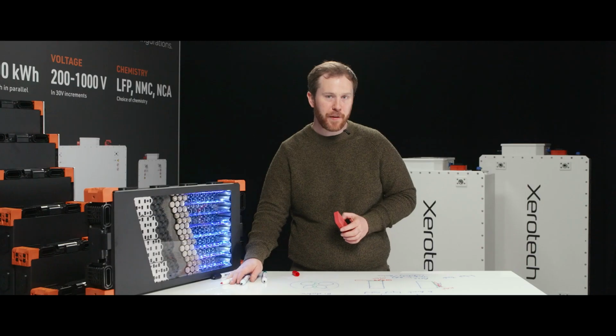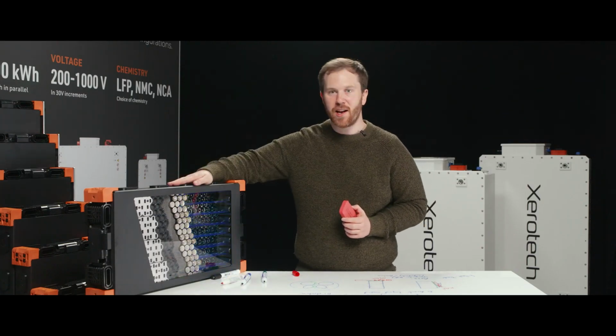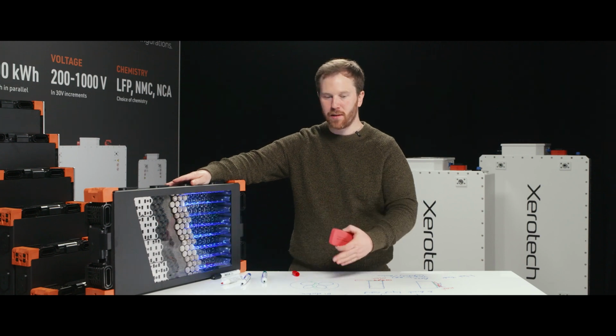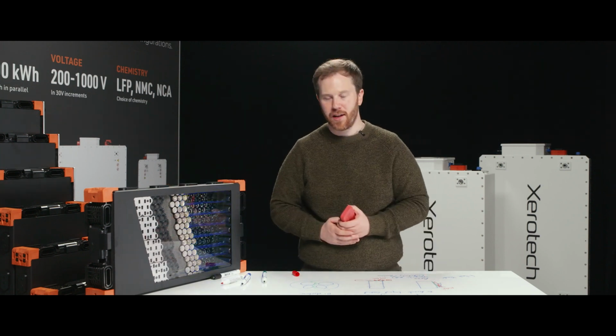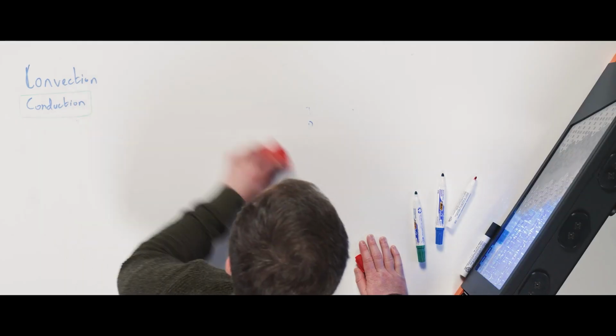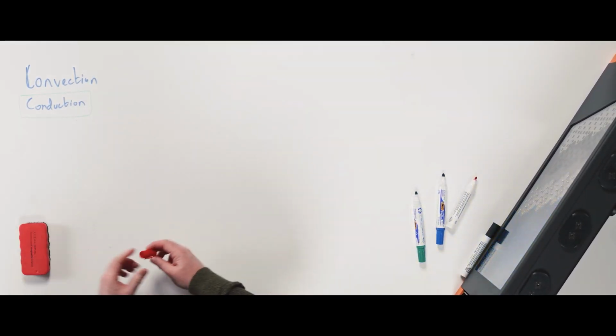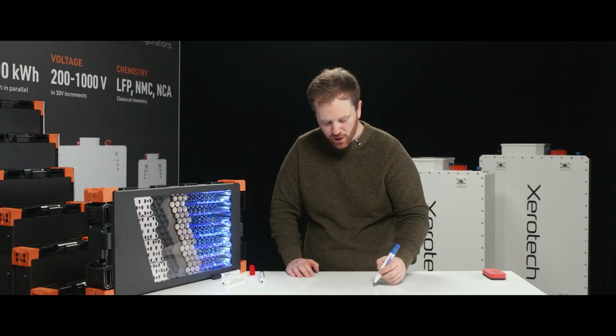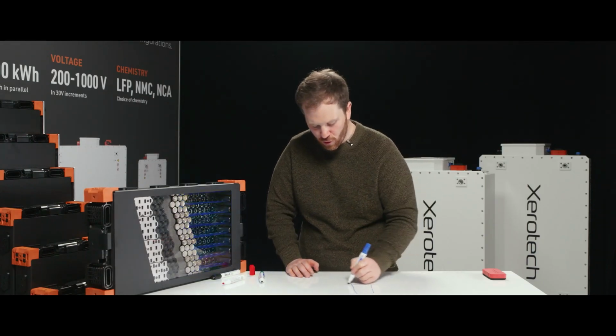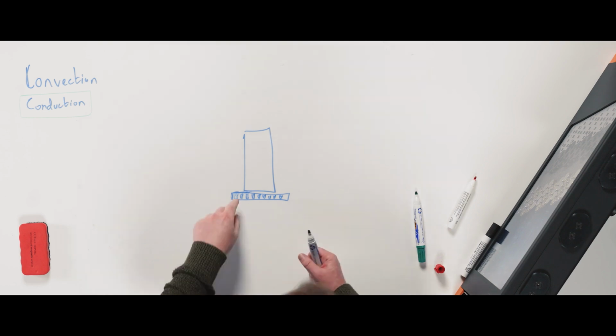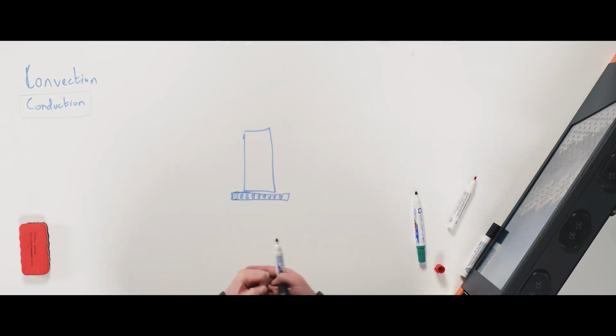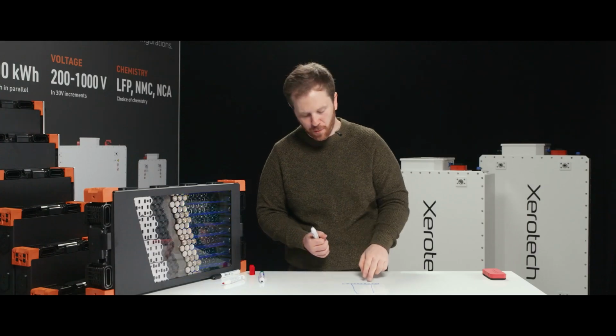We're going to go into some specific details now of the considerations of real battery pack engineering and actual practical stuff, now that we have a little bit of an understanding of the laws of physics here. One of the other factors you have to worry about when designing your battery pack is actually flowing the water through that heat exchanger. The vast majority of them are extruded aluminium heat exchangers, meaning there are little holes in them that they pump water through. And another law of physics to do with pumps is that you need a force, you need pressure, to pump water through something.